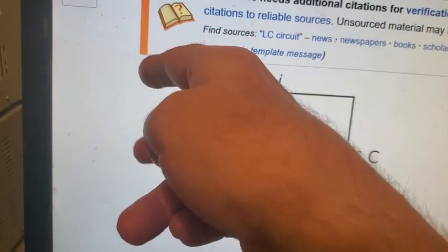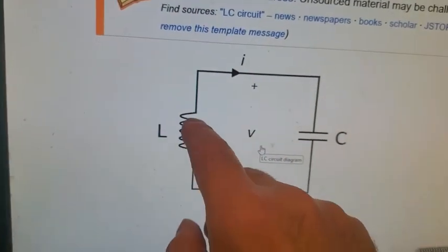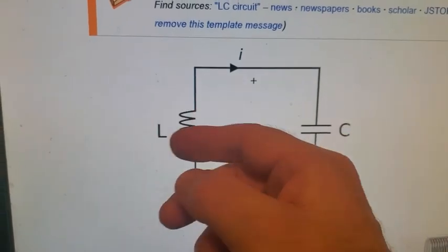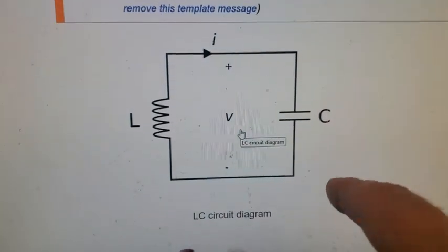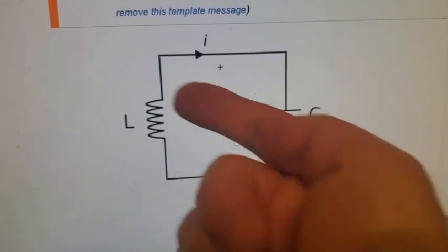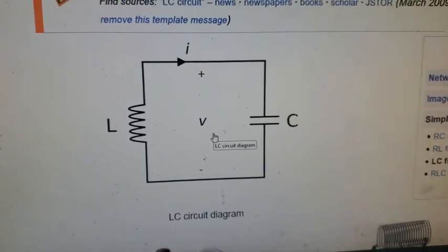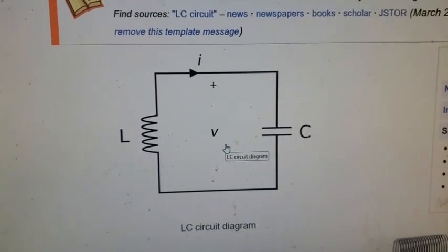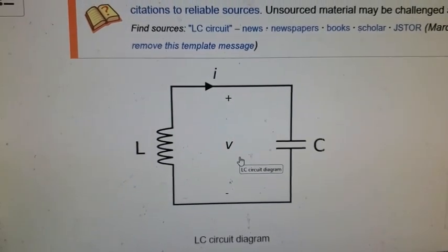And you can look at what shows up in the cap and maybe get 5, 6, 7, 8 volts or whatever. Then don't shoot anything out to the cap. Just let it shoot back here. And what that will tell you is how much you're losing from the diode and whether that's significant or not. So maybe it's imperceptible, maybe it's like 10% or something like that.